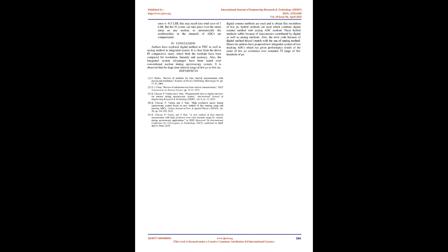It is observed that for a large time interval range of a few µs to a few ms, digital counter methods are used, and to obtain fine resolution of a few ps, hybrid methods are used which combine the digital counter method with the analog ADC method. These hybrid methods suffer because of inaccuracies contributed by digital as well as analog methods. Also, the error code because of the digital method doesn't match with the one of the analog method. Hence the authors have proposed a new integrated system of 2 tracking ADCs which has given performance results of the order of a few ps resolution over an extended TI range of a few hundreds of µs.